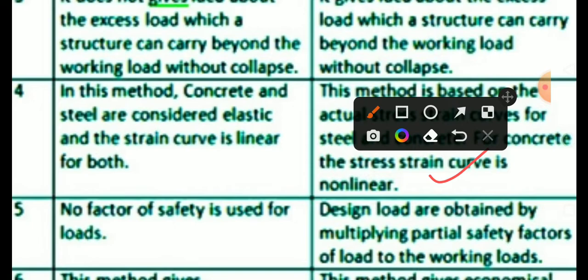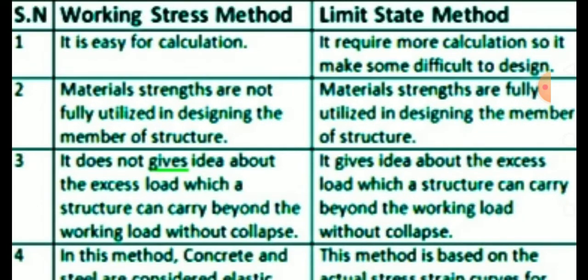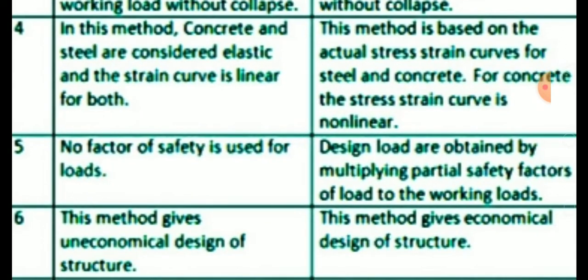Point number 5: in the limit state method, design loads are obtained by multiplying partial safety factors of load to the working load. But in the working stress method, no factor of safety is used.